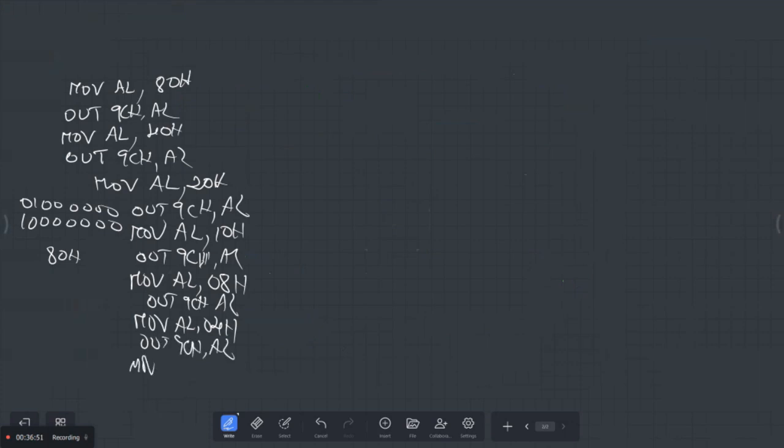Next, move AL, comma out 9CH, comma AL. Next, move AL, comma 01H, out 9CH, comma AL. Done. Now, how do you repeat it for n number of times?